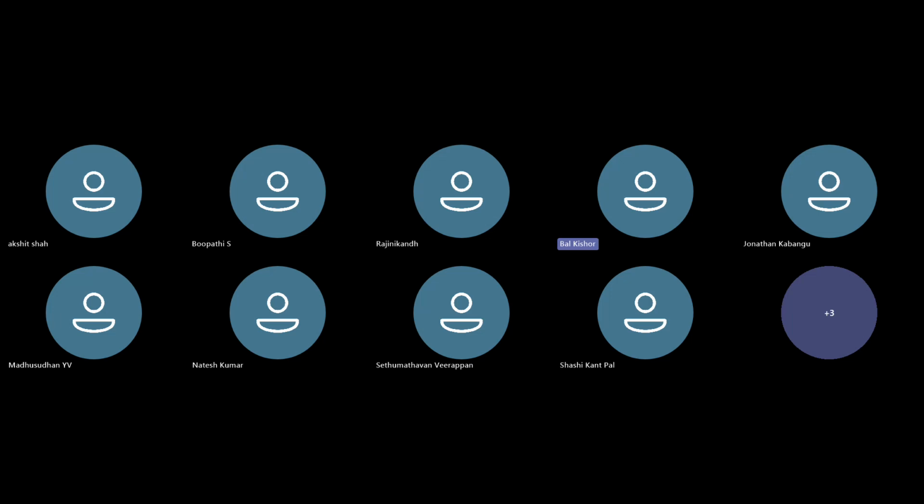If you want to see the complete voltage range, you can just right click on this scale and set the top and bottom scales. So let's say I want to start from 0 to, let us say, 6 volt at a step of 1 volt. So it is showing you 4.3 and 5 volt. Got it? Right. So this is how it works.